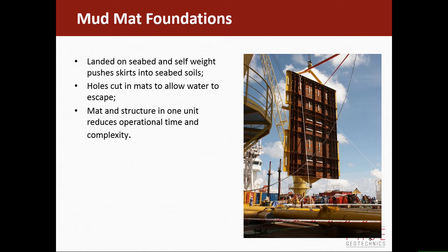One thing to watch though is if you do that, when you land it on the seabed, there's water inside those skirt compartments, so you have to have holes to let the water out. And I have seen people ignore that, and then on a sort of 2-degree slope somebody had a structure which slid off about 100 yards before it stopped, and they wondered why.